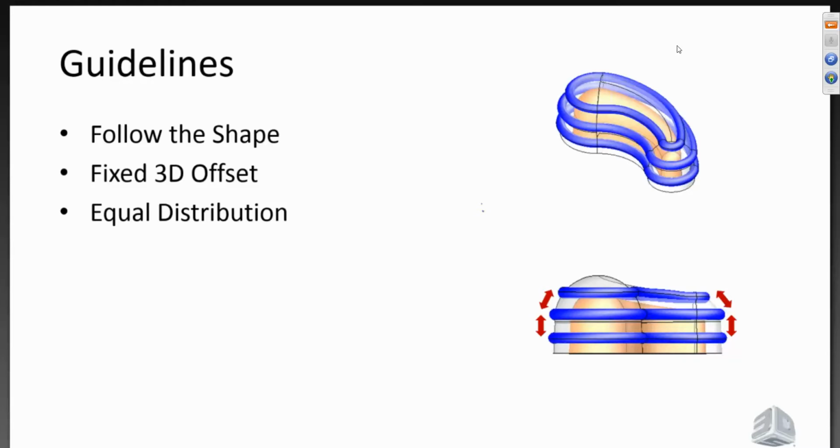That's the true distance off that part. So we'd want the water line to follow that and stay glued to that. And the arrows kind of show you how by that shift we need equal distribution, which means that the water line is going to drift in a bit. We're not so concerned about keeping everything planar. What's important is keeping the distance between things around the surfaces of the part geometry.